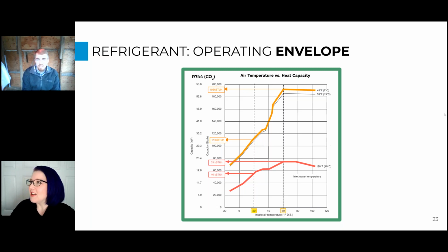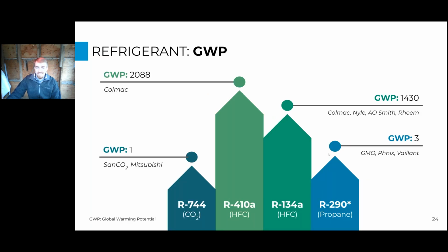Yeah, that's correct. So if we're heating water up from 45 degrees up to 140, the water entering that heat pump, it's really easy to dump heat into 45-degree water. But once that water temperature increases, it's a little harder to dump heat into that. And then the CO2 refrigerant cycle, which I'm not going to get into because it's really complicated, is a lot worse because of the phase change that it has to go through and that the higher entering water temperature doesn't allow. So the simple answer that I over-detailed there was: higher entering water temperature equals lower COP, or efficiency. Yeah, great question.